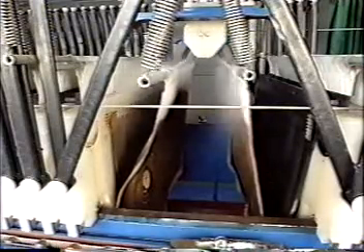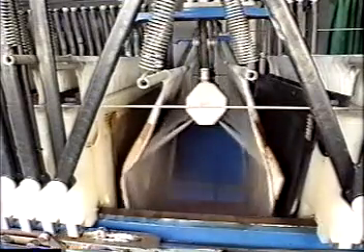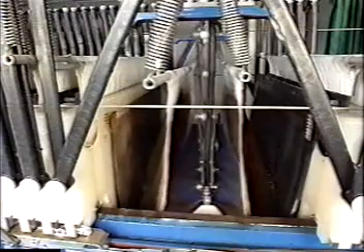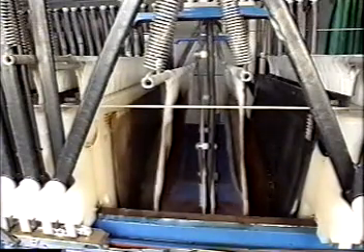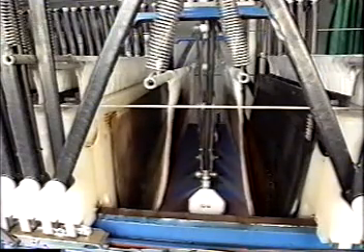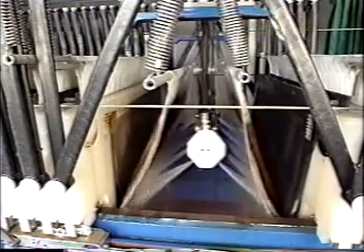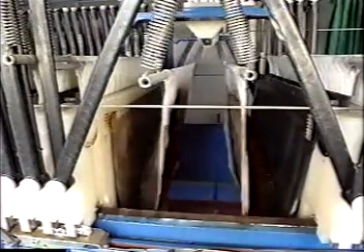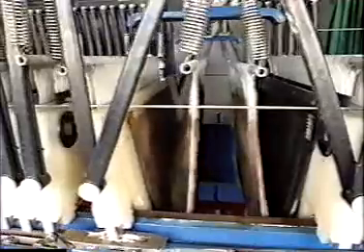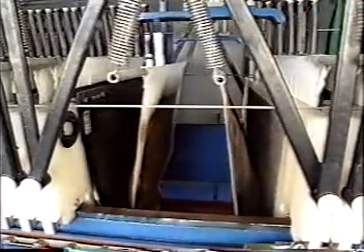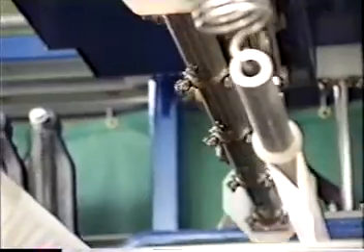After sensors confirm that the nozzles have been positioned in the center of the open filter chamber, the nozzles are lowered. A sensor in the washing unit detects the filter cloth surface, and washing fluid is sprayed at a high pressure of 40 kilograms force per square centimeter. After washing one chamber, the filter plate moves to open the next chamber. In this way, the filter cloths are washed one chamber at a time.